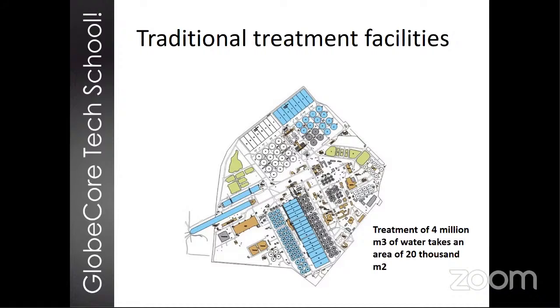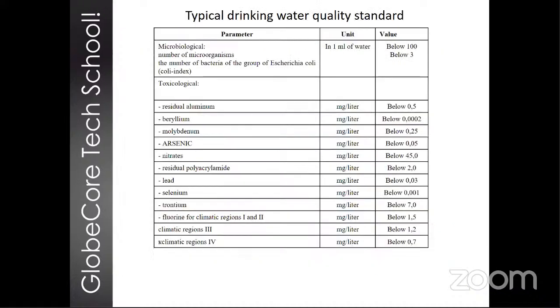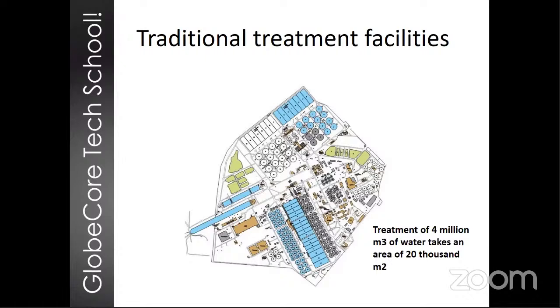And this means that if the source water contains any soluble salts, for example, salts of heavy metals or phosphorus or arsenic or what have you, the size and cost of a facility to process such water can double or even triple. And at the same time, even if we increase the size of the facility, we don't necessarily have the ability to improve the degree of water purification. Next slide, please.